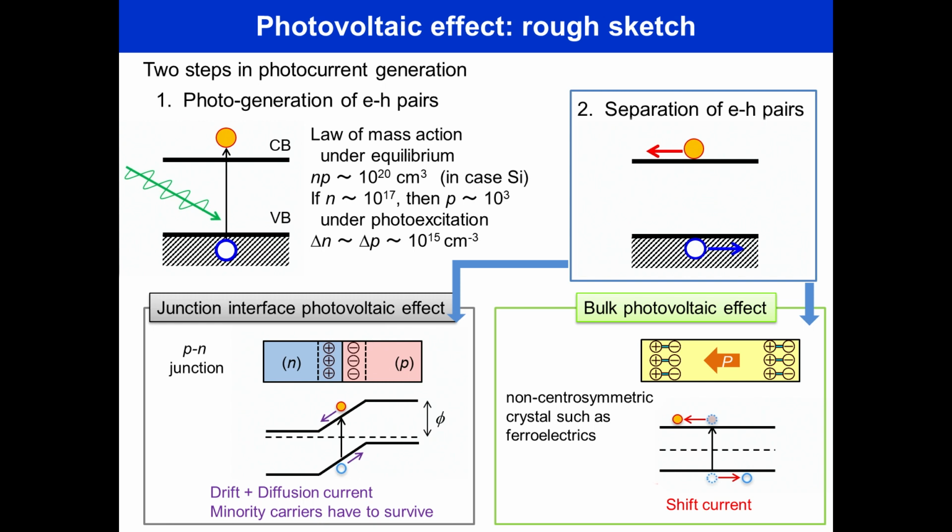One is that semiconductors have a gap of about 1 volt between where electrons are and where electrons are not, which is called the forbidden band. If the energy of the light is greater than 1 volt, an electron that enters this bottom is knocked up by the light with a pop and jumps up. The vacancies of electrons that have been created by the excitation are called holes, and they tend to have a positive charge against the electrons' nature of having a negative charge.